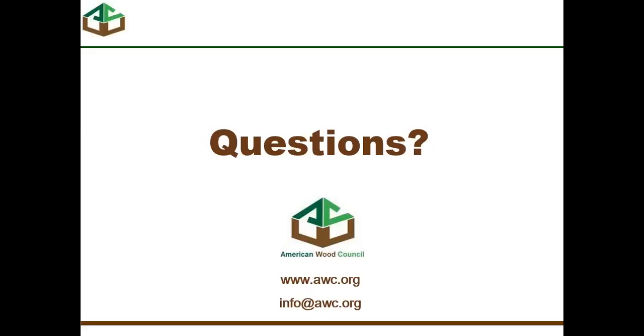Very good. Thanks, Bill. Here's another question. With nail guns being so popular, would you like to say a word about the nailing as prescribed in the wood frame construction manual and what we might find actually being installed with nail guns? I probably can't say just one word about it. I guess what I would say is that the capacities or the resistances that are suggested in the wood frame construction manual are based on a certain nail size and length.